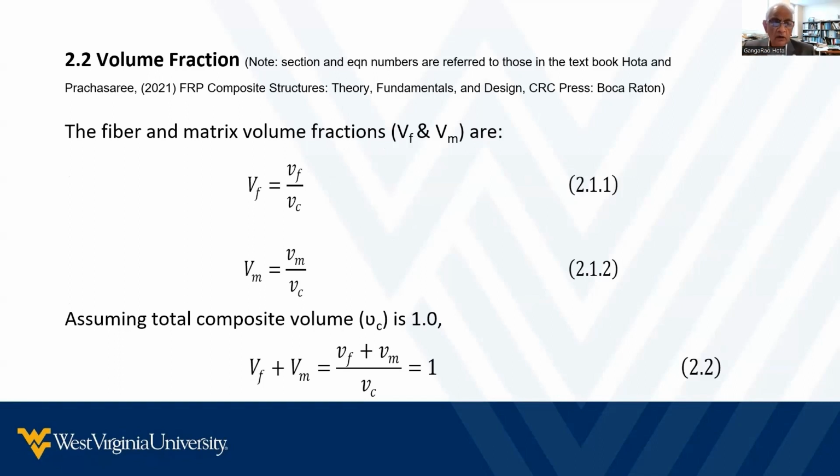Now, let me define first what is a fiber volume fraction, what is a resin volume fraction, before we figure out very, very simple mechanics-based approaches to find the modulus and the strength in the longitudinal and the transverse directions, as well as the Poisson's effects, and shear modulus.